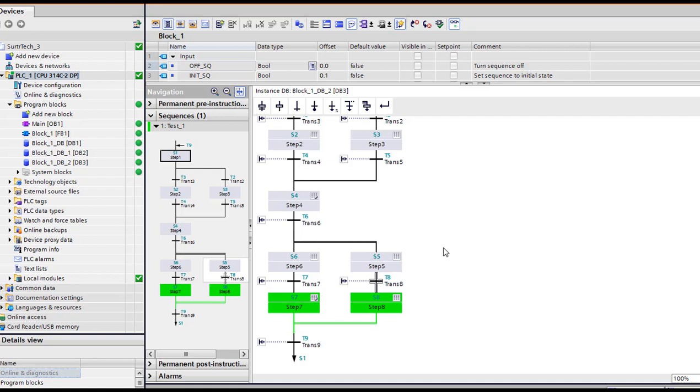So as I said, if you have a motor activated here and another motor activated here, but this one you want to turn off, you should add a blank step here so the program gets shut here. Or if you use set you should use reset here, or if you use N here you can use the blank step. So if you want to wait until the other one which has 10 seconds here, you can use this method. It's a simple method and useful in other projects.